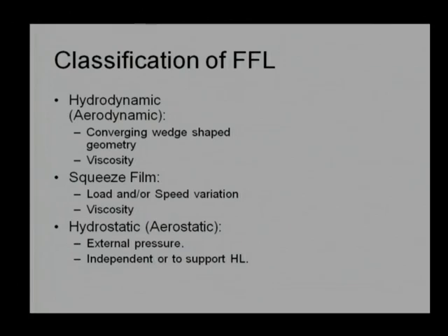The basic assumption in these equations is that the gap between two metal surfaces or two material surfaces is infinitely small, maybe in the order of microns. It can go even to nanometers or to mm, but the overall size also will grow or reduce accordingly. So, to start with, there is a classification of FFL, as fluid film lubrication.